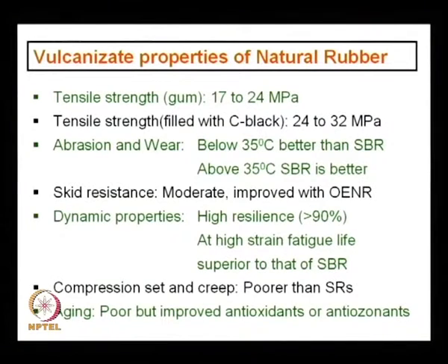Stress your load, applied load, then after application it is released. So, continuously it is application and release, application and release. So, this kind of cyclic load is there. This is called dynamic stressing, and that is actually evaluated in the laboratory in simulated condition by a flexing machine or fatigue to failure machine.